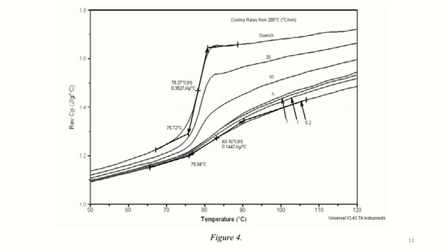One of the most difficult measurements for differential scanning calorimetry is the detection of small amounts, which we can say is less than 5%, of amorphous material in highly crystalline samples.